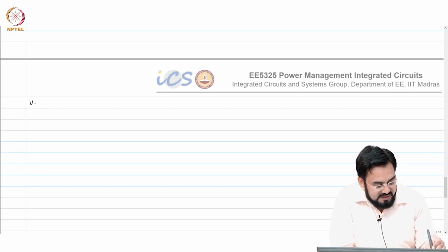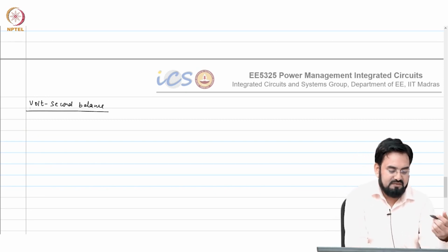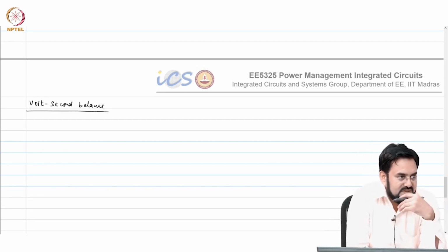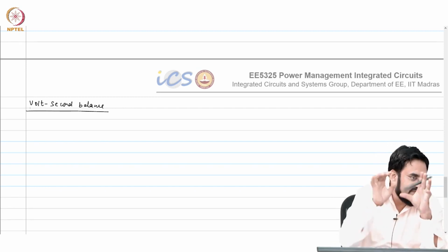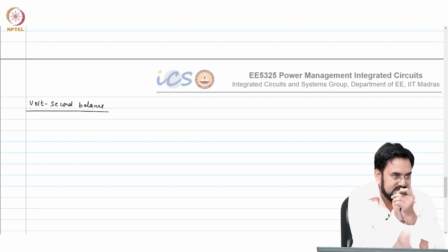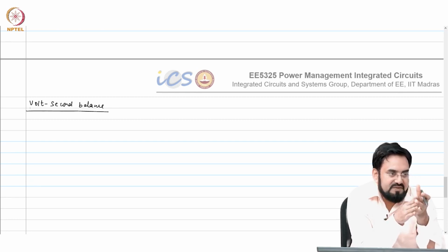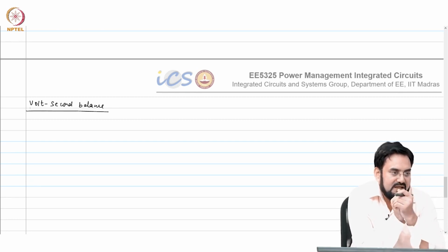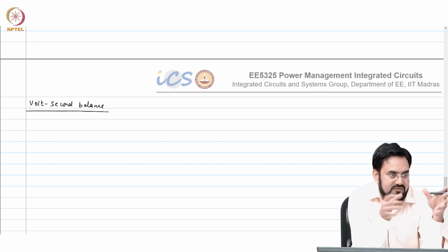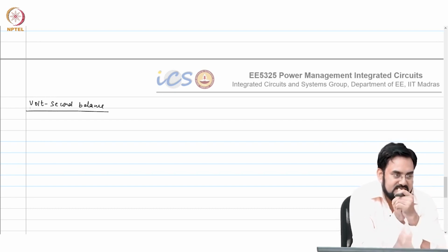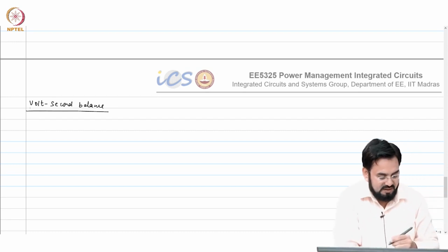So there is something called volt second balance. For this particular case, you already know that your output is D times VDD, but there might be some different architecture where you don't know the topology. In order to find the relationship between V out and V in, that's what we use, volt second balance, and irrespective of what kind of configuration you have in the power stage, you can always derive that using that formula. So let's see how it works.